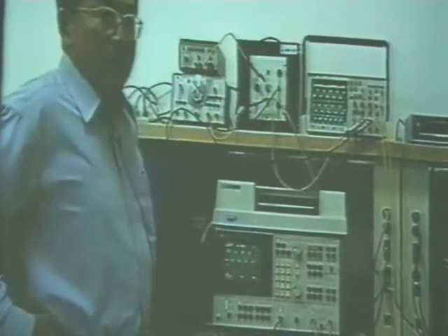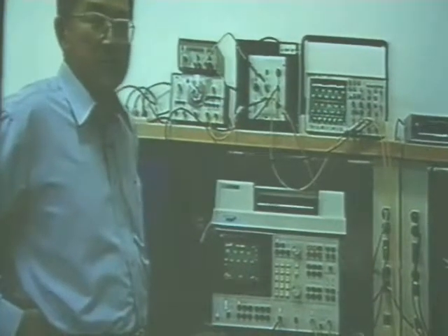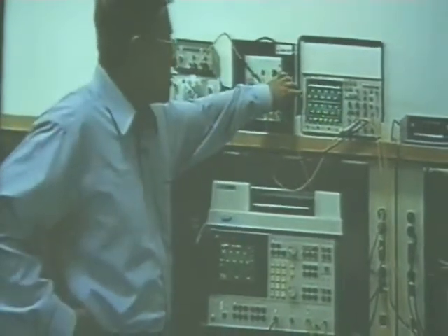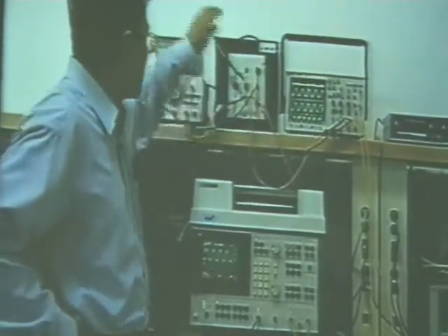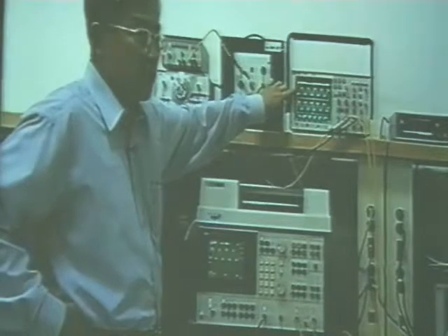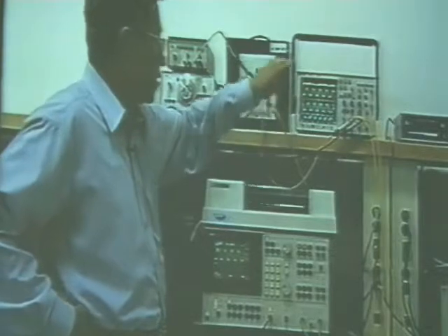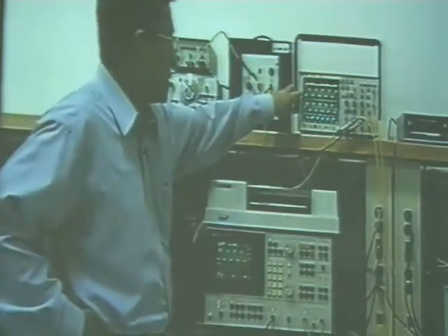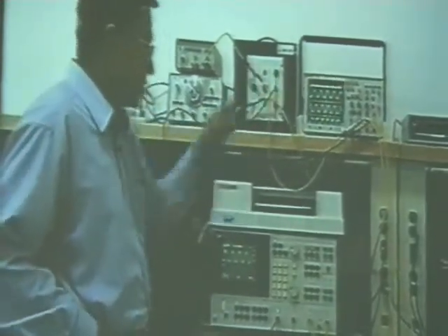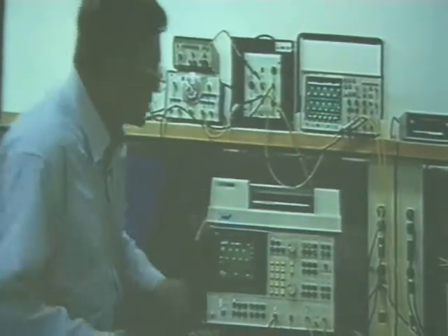I'll give you a demo. First, I'm going to show you the autocorrelation function measurement, which is RXX. So I'm going to use only the top signal, which is coming from box A. This happens to be the sine wave. So when you take the autocorrelation function of this harmonic function, the result, if this is sine, is cosine. That's what we know.